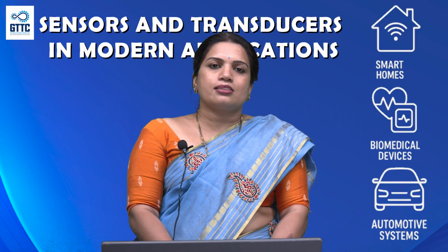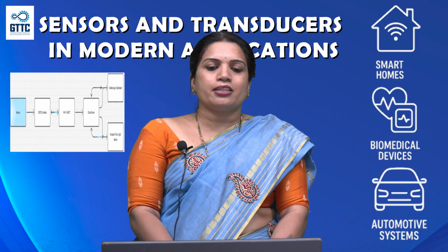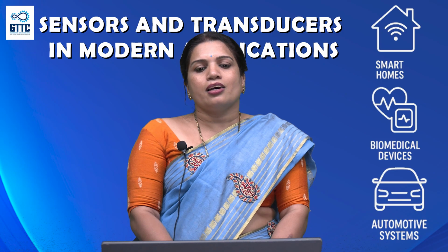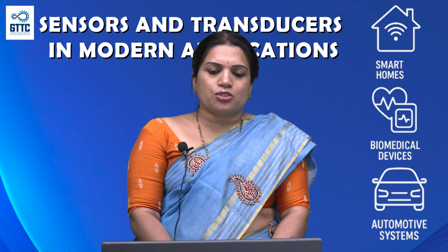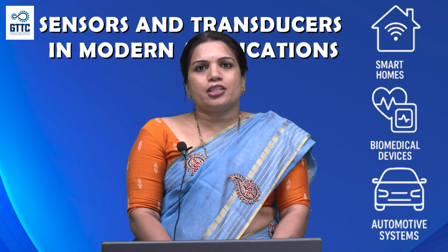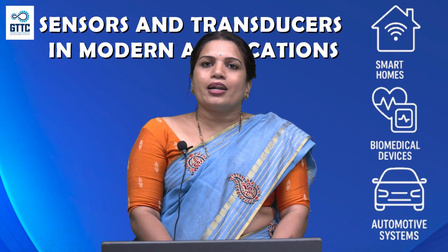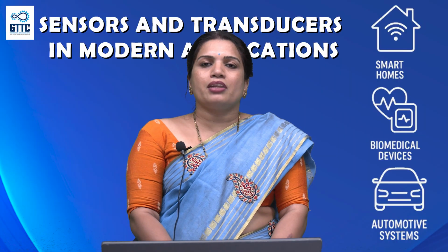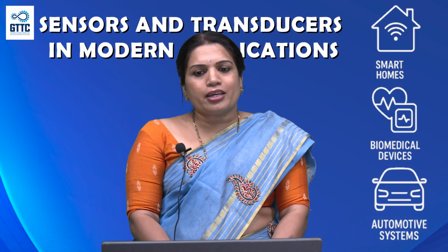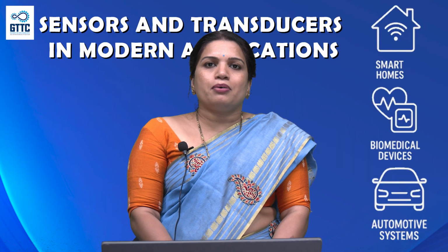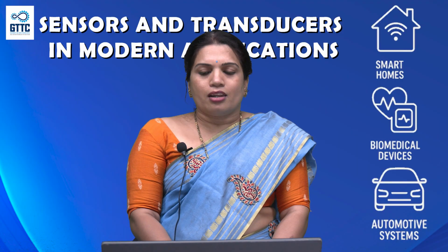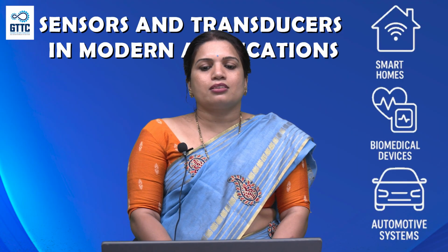The sensors detect the physical parameters, and the electrical signal generated at the sensors is given to the microcontroller. Here we are using a microcontroller like ESP32 or Arduino, where the programming happens and the data is processed, and the output is given to the mobile app or the actuators like fans, lights, and motors.